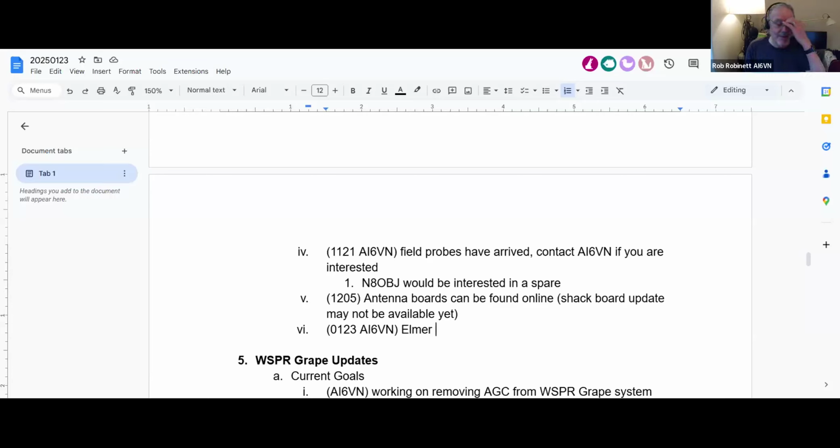The solution is pretty straightforward: shorten the dipole. Instead of 6 meters, make it 3 meters. But through this process, we've identified one criterion we need to use at sites: we need to know what the peak voltages are at the antennas. It's not just AM stations.